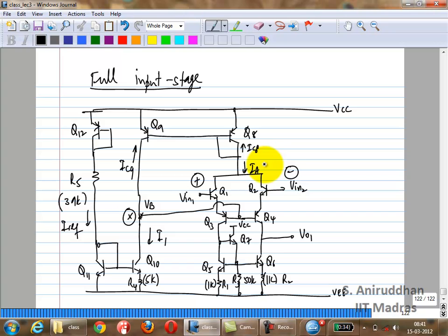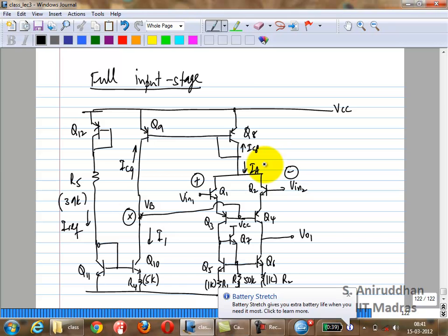And what we'll do is, when doing that, we'll assume a number of things. So first of all, the first thing we're going to assume is there is some overall feedback around the op amp, which is going to set the output common mode to 0 volts across the overall op amp. This is just the first stage. Okay. So now, then we'll ground the two bases of the inputs, and then we'll start analyzing what the currents are. That will be your steady state, right?